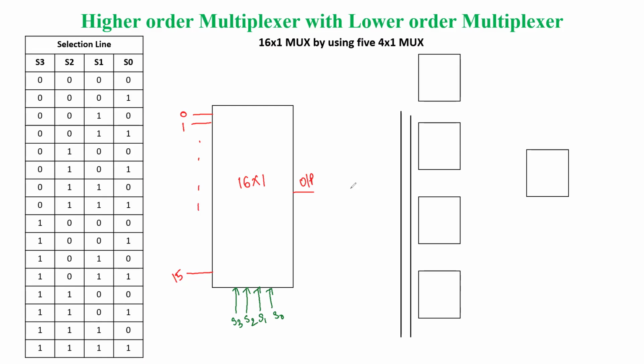Now the same behavior we should get when we write this with the help of 5 multiplexers. If you see, at the input stage we have taken 4 multiplexers. These are the 4 cross 1 multiplexers. At the first stage we have 4, and finally the outputs of these 4 multiplexers are going to combine with the last multiplexer, which will be our 5th multiplexer.